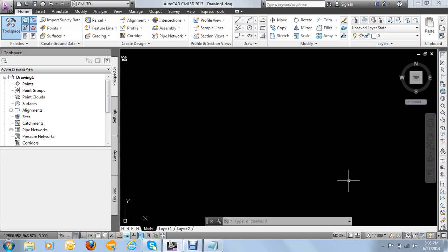So we are going to design the corridor, but before designing the corridor itself, you have to design an assembly, and in that assembly you have to know the standards of the lane that you're going to use, or the shoulders, or the ditches, and all those. So what I'll do, I'll just create several assemblies together. You'll see, you can ask some questions that you think you can ask.